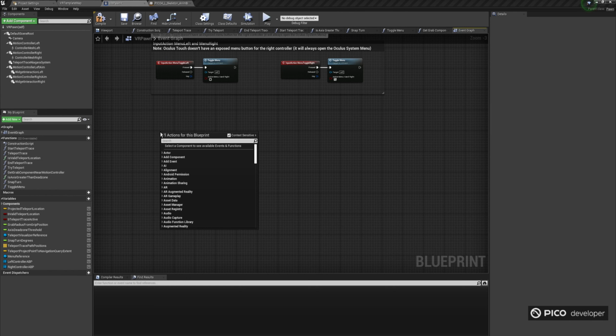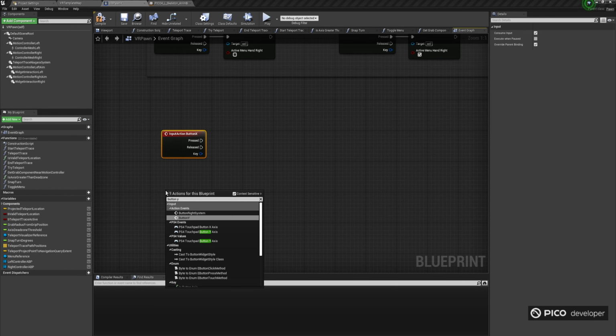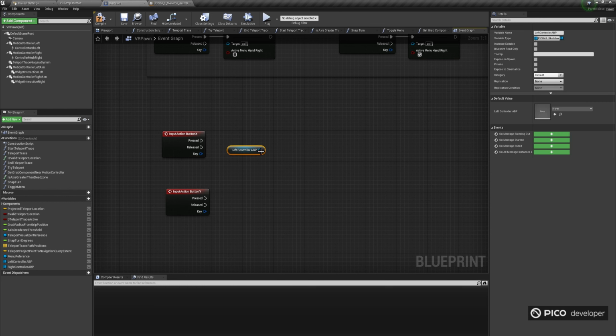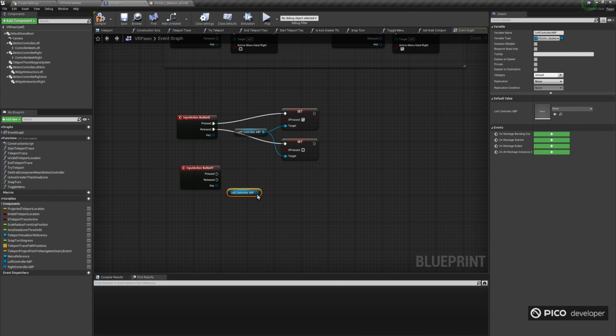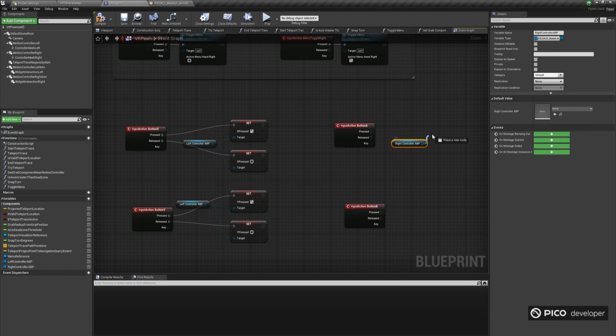Now we will use the input events and connect them so that they automatically update the values of the animation blueprint instance variables. Go ahead and do that for all the available animation blueprint variables. I'm going to fast forward this video, but feel free to pause to actually see the changes.